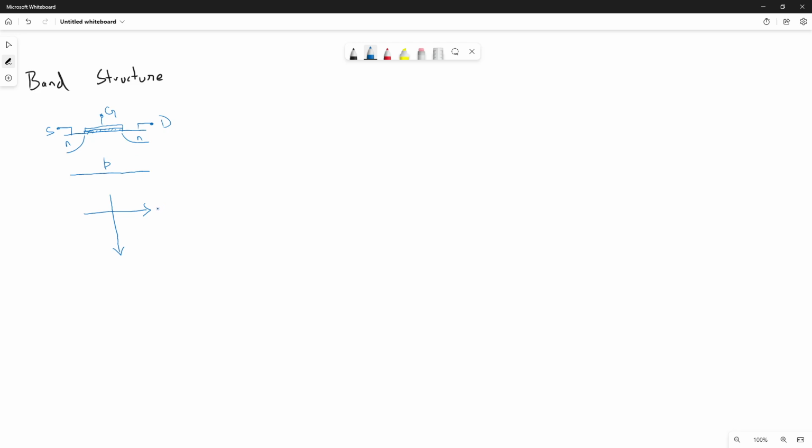Okay. So now I'm establishing the direction convention. Whenever I'm going to write an X direction band diagram, I'm going to talk about the source channel drain relationship. And by default, the positive y axis is going to go downwards. So the y axis starts from the gate, goes through the oxide layer into the body. Okay. So now let us look at the X band diagram.